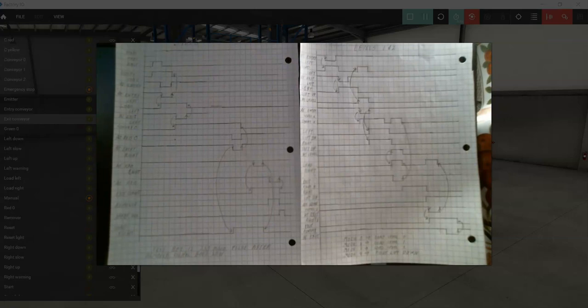Now the last thing is to keep going as soon as it gets removed. As soon as the remover finishes, we have this little signal here, which is hard to read, but it says next box. We set that up with a pulse timer, and I have it set up as 250 milliseconds, and it's a pulse after the remover signal goes low.